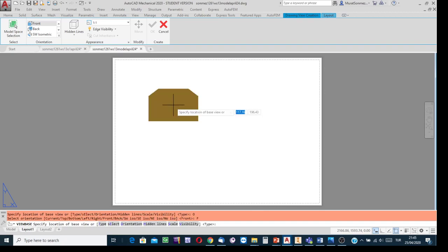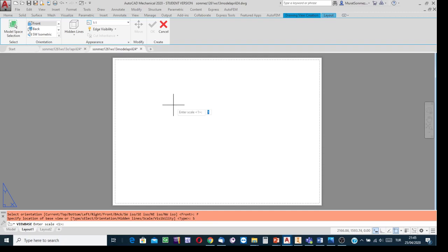Select with a click. I said that is the side of the object. The front side of the object, and that simulated one, is the front side view. And then the scale factor. Click on the down direction key and from the list, in that case, select not orientation but the scale option. Well, I see that for the simulated view, the scale factor is 1. I checked it already. A scale factor of 1 to 1 is suitable regarding the order of magnitude of the object and the working space of the paper. I am going to use it. Otherwise, I will change the number.